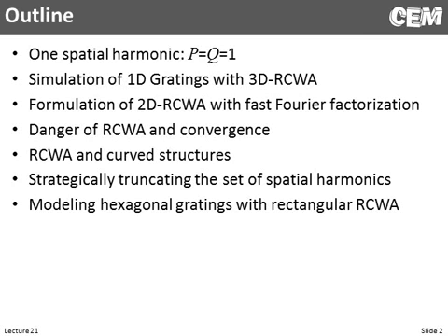Next, I want to move on to using a fully three-dimensional rigorous coupled wave analysis tool to model a 1D grating, which is a rather simple case, but we can do it pretty efficiently still with a three-dimensional rigorous coupled wave analysis, and we'll borrow from our discussion of this one spatial harmonic thing. And this is almost to the point where it's not worth developing a two-dimensional RCWA for modeling 1D gratings because the 3D is so fast and efficient. However, if we're lumping our model into an optimization that iterates a million times, maybe then it makes some sense to develop a two-dimensional RCWA, which is our next topic.